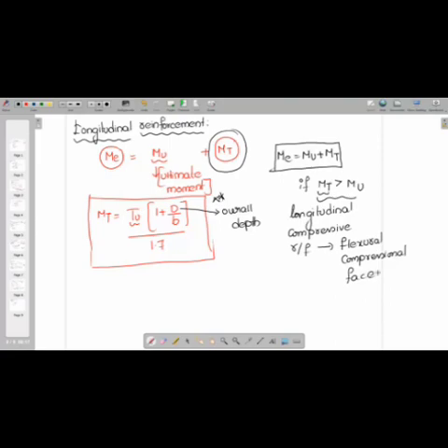These will be provided on the flexural compression face. Here, how do you calculate the equivalent moment? You will be designing the longitudinal compression reinforcement. Me2 is equal to moment due to torsion minus ultimate moment, because moment due to torsion is greater than Mu. You will be designing for this only.